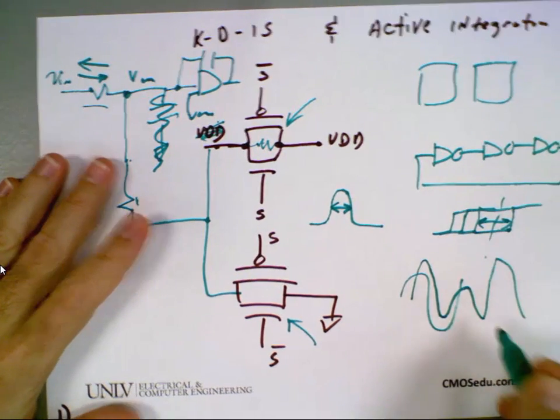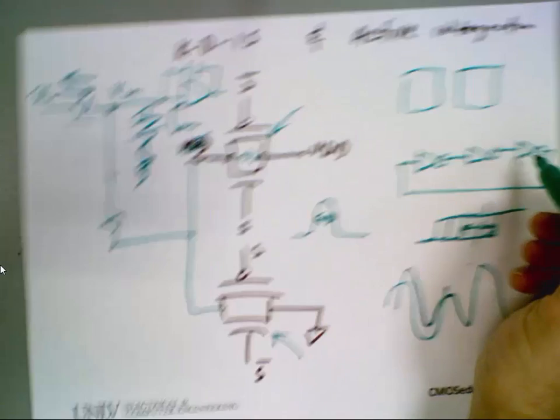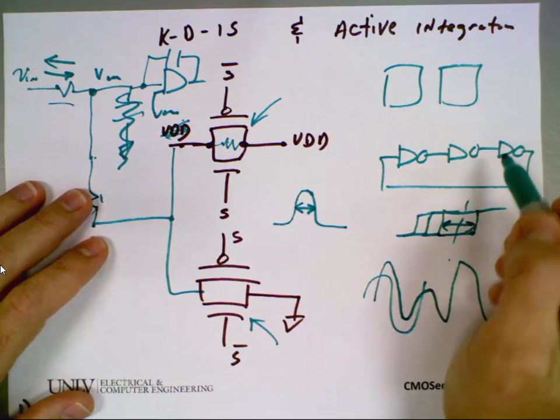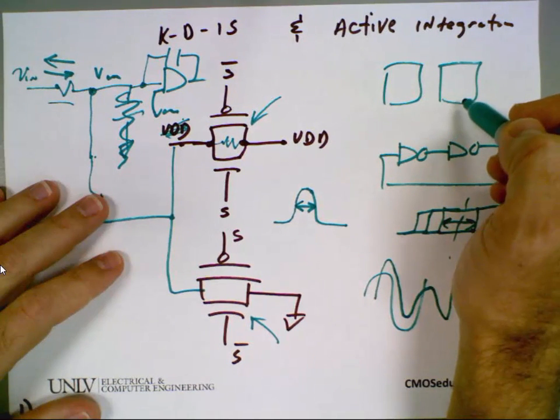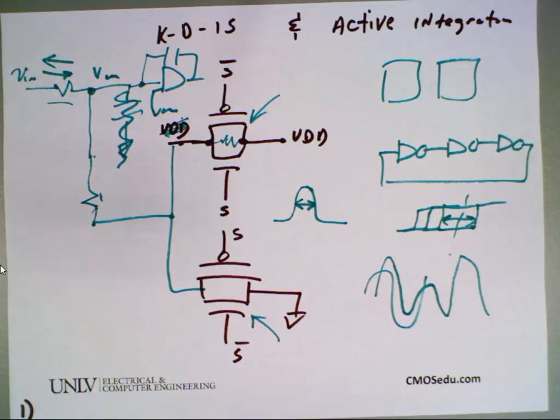And then the amplitude will be modulated. So you got to make a ring oscillator. That's one of the reasons I put that one in there that doesn't use an odd number of stages. So you basically have to use like the NAND gates or something like that with the cross-coupled feedback, okay? So just like I had in there where it's the latch, you feed everything back and it gives you nice, well-defined edges, okay? Are there any questions about that?